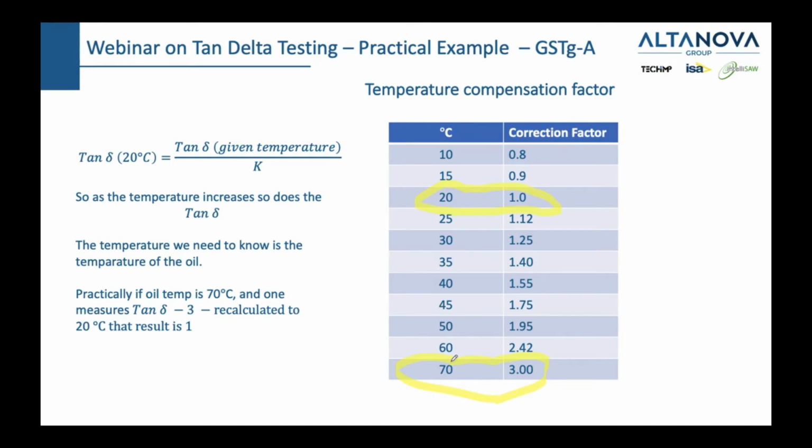You simply read it from the gauge which is installed on the transformer, and you factor that in after you measure the tan delta. Because if it's 50 degrees outside and you got, let's say, 1.8, it doesn't mean that your high voltage transformer has a problem. It simply means that you need to compensate for that temperature using this formula here. So I hope that that is clear.